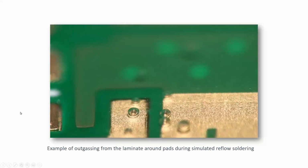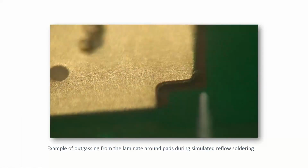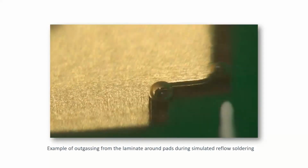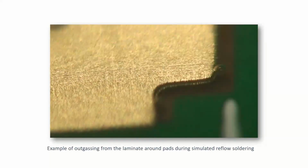So I've got oil, I'm heating the board up on a rework system, and you can actually see the gassing taking place. So this isn't actually on the pad, but it's around the pad surface. Now, whether or not that would impact the amount of voids that you might see, I can't guarantee that. But again, that's just another experiment.